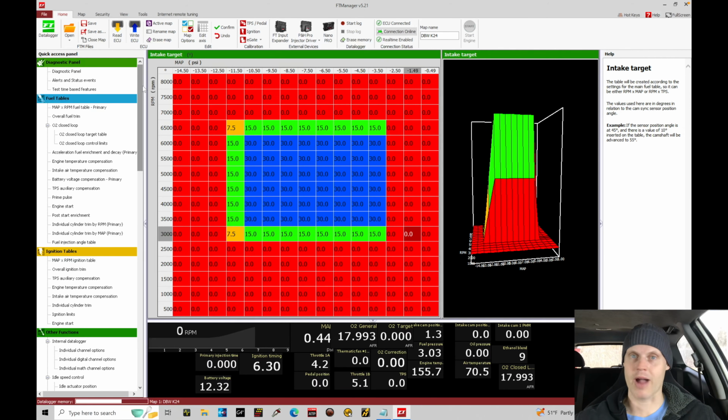And then we'll just kind of rapid fire through all the changes to see how this is going to go from start to finish. We're going to have really poor, probably lackluster power output out of the engine. That's fine to begin. And then as we start to make our changes towards the end, we should see a pretty substantial difference in power output once we have that variable cam composite blend built, and we also have the spark timing dialed in. So we have our cylinder pressure in check, and the engine should all be dialed in at that point. So let's jump here and take a look at the Mainline dyno screen, and let's set everything up here.